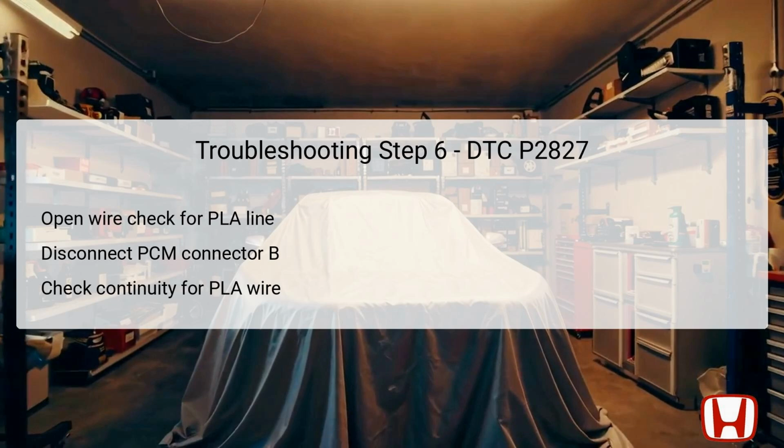With both the line pressure solenoid valve A 2P connector and the PCM connector B disconnected, check for continuity between test point 1 at line pressure solenoid valve A 2P connector number 1, and test point 2 at PCM connector B, number 5.